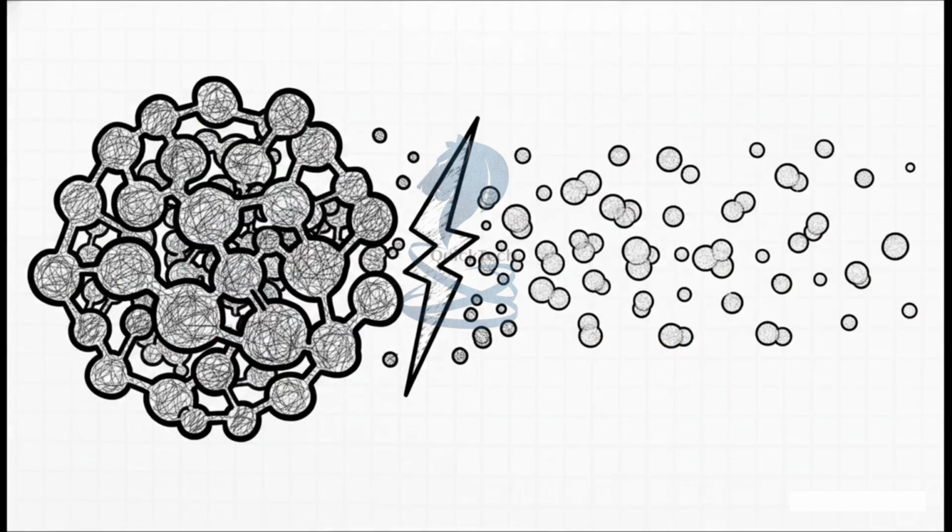Now, as comprehensive as this main tower is, the initial fractional distillation is really just step one. You'll also hear about secondary refining processes, things like catalytic cracking, hydrocracking, reforming, and delayed coking. Why do we need these? Well, the global market often demands way more of the lighter fuels like gasoline than raw crude naturally has to offer. So refineries take the heavier outputs and use these highly advanced secondary chemical processes to literally break apart, or crack, the heavier molecules into lighter, much more valuable ones. It's a real game changer for meeting our modern energy demands.